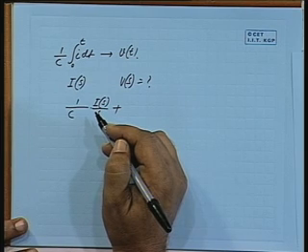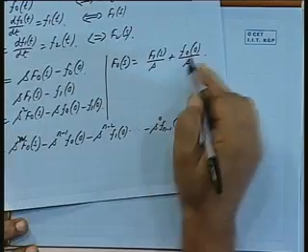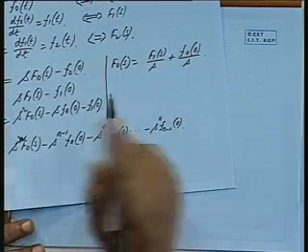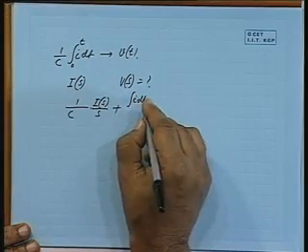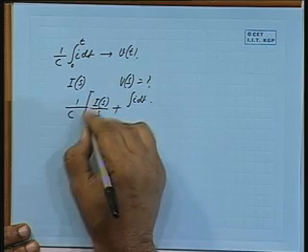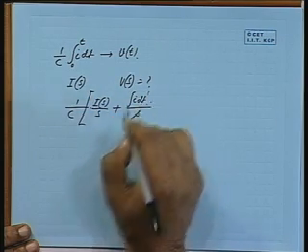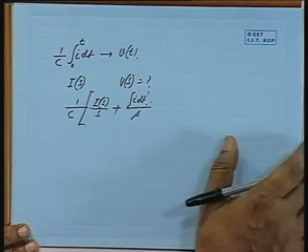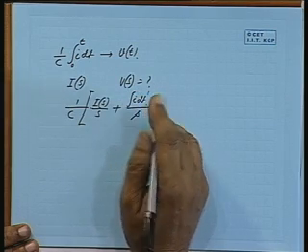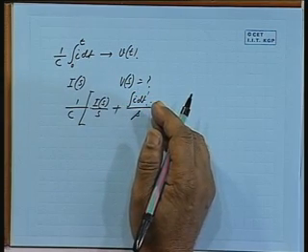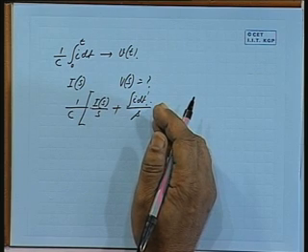What is f0? It is the integral of that. So, integral of i dt, divided by s, and this is to be evaluated at 0. From where do we start? From 0 minus to 0 plus, or basically whatever has been there before the counting of time, before t equal to 0.